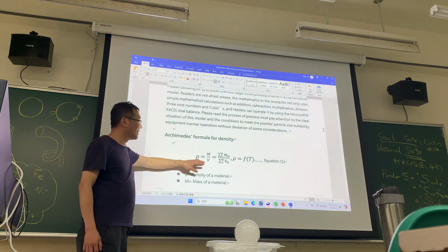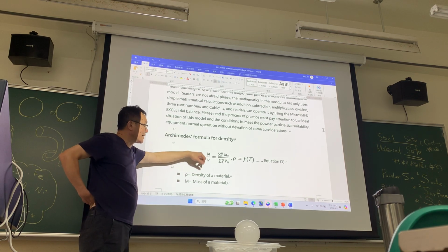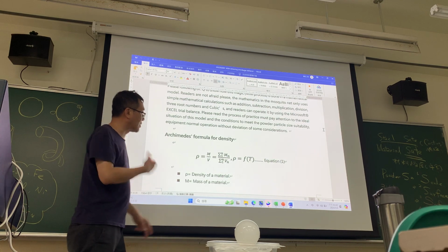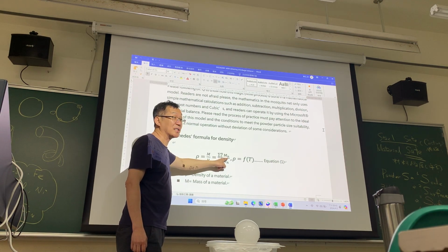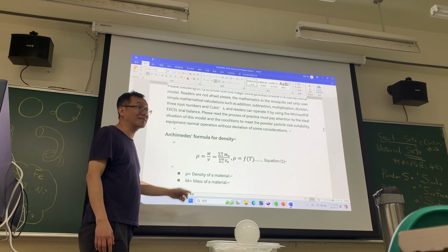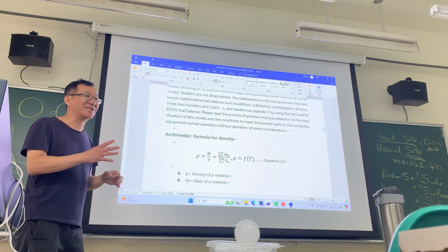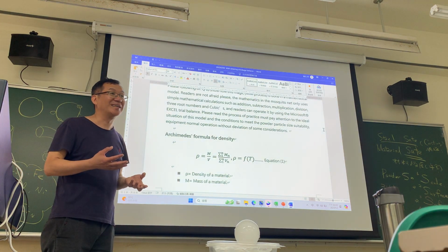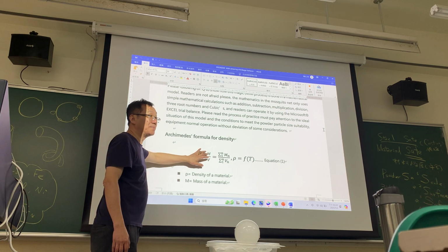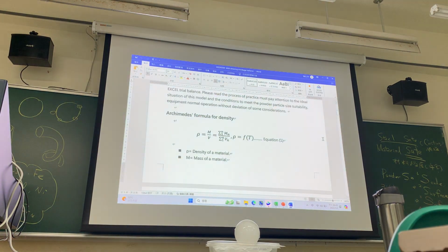These equations mean density equals mass over volume. And this one is a summation. Summation means you have different materials, so you have different material volumes and different material weights. Then total them together, and you can get the final density. Understand? So this one is a test. Then the team will make some error, and you show the calculation of density of error. Very easy, right? Just a calculation. How to exchange weight percent to volume percent is very important. Those are the two keys. Let's go next.